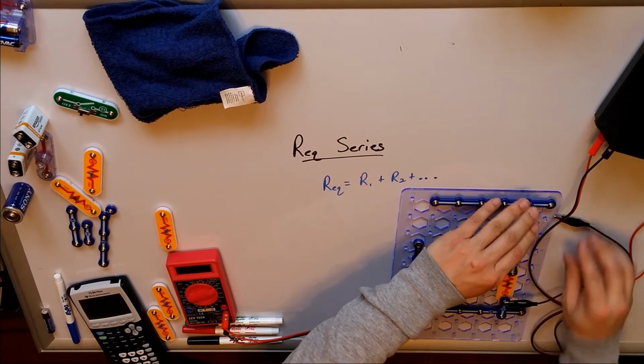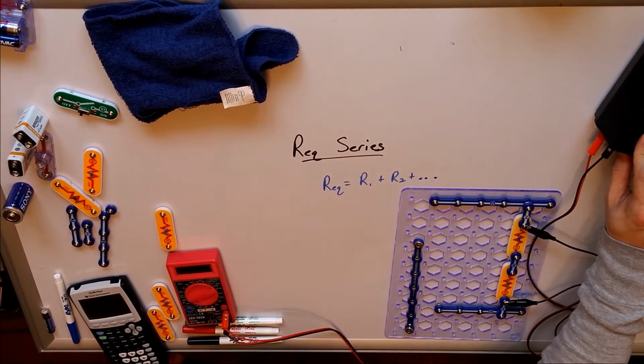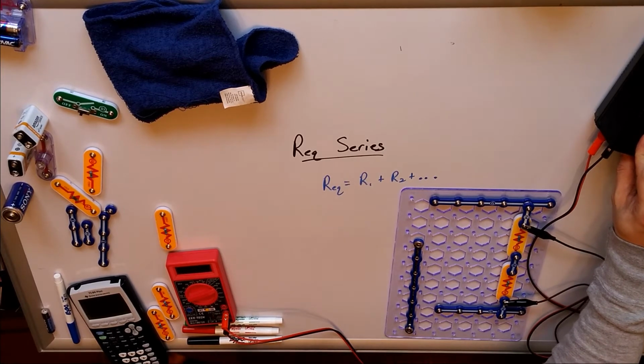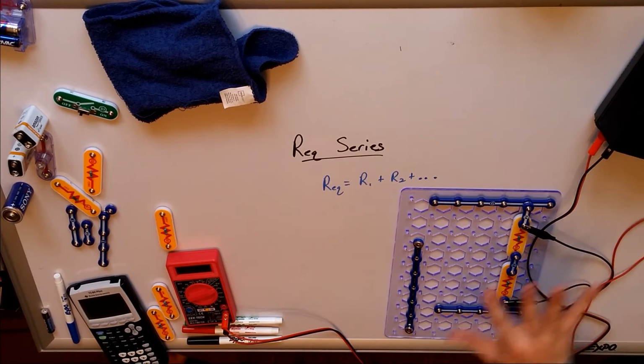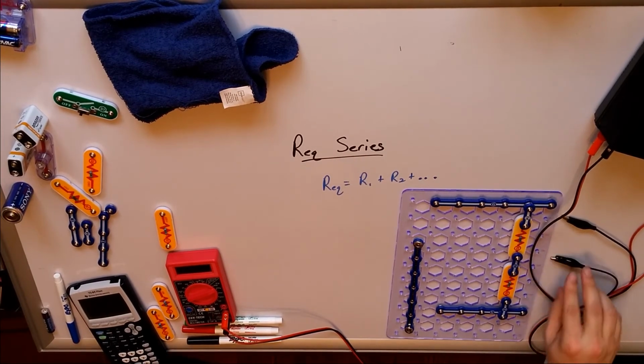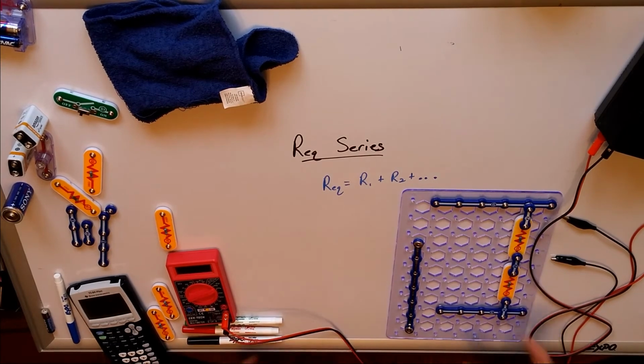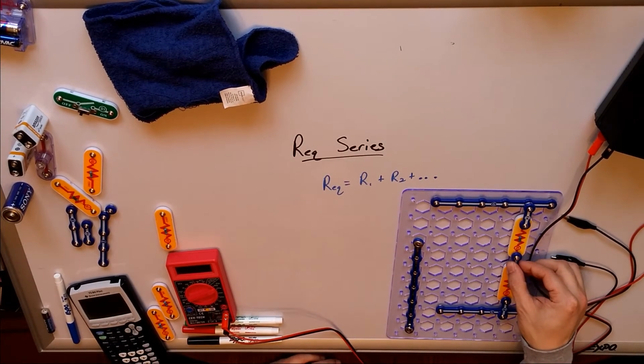We should end up with something in the 480 microamp range. Let's see. 482 microamps, so we're staying exactly the same. Order does not matter on which one comes first and which one comes second, because as charges move through the circuit, they're all moving together. Everything is happening at the same time.